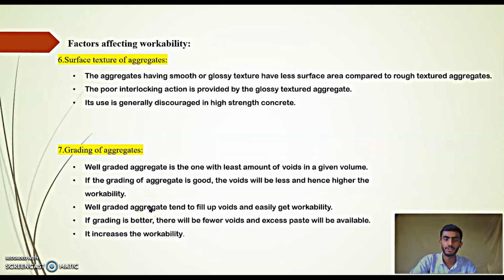Well-graded aggregate tends to fill up voids and gets easily workable. If grading is better, there will be fewer voids and excess paste will be available. Therefore, grading should be better provided in the aggregates. It will increase the workability.